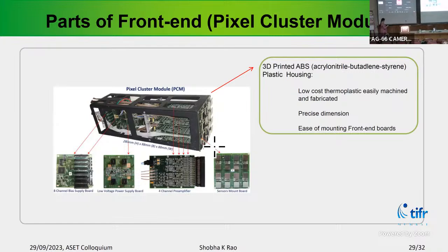Can I ask a simple question, Shobha? Why didn't you adopt an ASIC-based imaging system rather than making your own amplifiers and so on? They are available now, 128 channels. The size is just like a nail. ASIC, first of all, ASIC design was custom designed for particular experiments, and they were very costly.